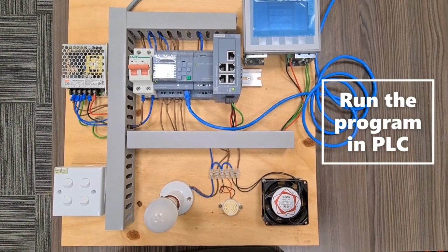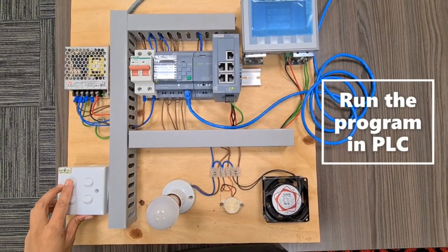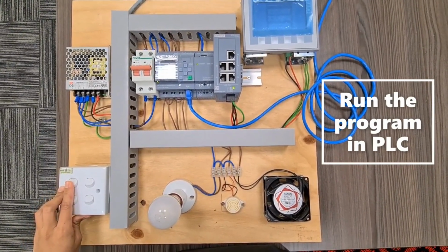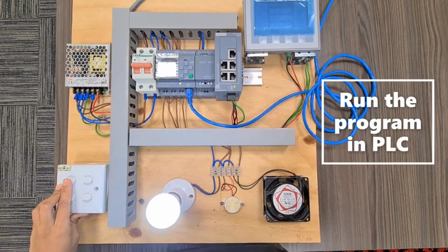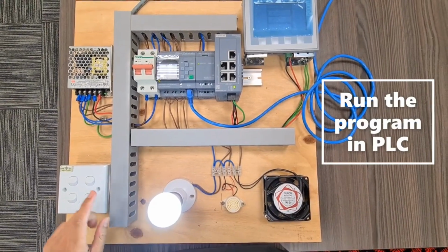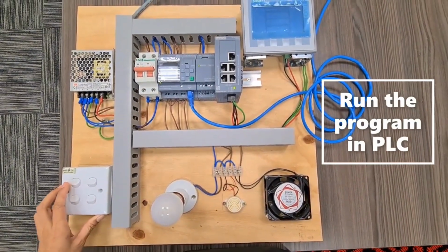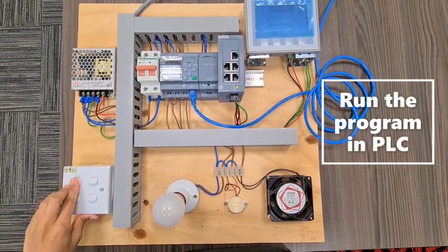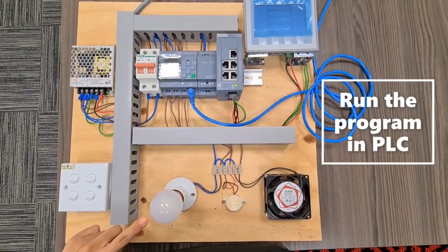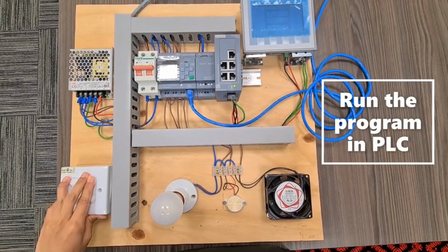Now we will test the actual PLC circuit. I will press the I1 button and release it. After 5 seconds, the lamp should turn on. And now the lamp is turned on. To turn it off, I have to press the stop button and release. And we repeat the test again. Press I1, release. After 5 seconds, the lamp should turn on. And then use the I2 button to turn it off again.